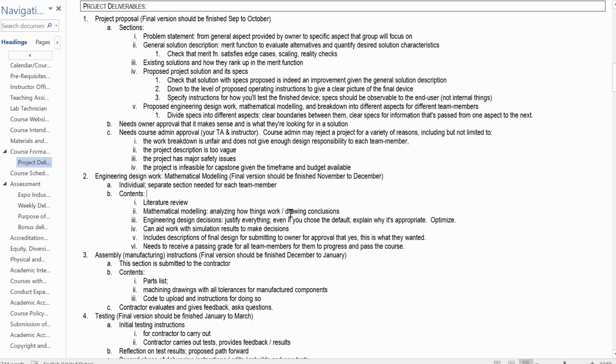So I realize that sometimes it's very difficult to model things. If you've already built the thing, it's hard to get help from this model. So definitely you're going to want to do this design work ahead of time. Imagine you didn't spec out the pump very well. You just kind of bought this pump. Fine. Okay. What could you do? You could calibrate it. Well, one way to calibrate it is with kind of an experiment to see how much water goes through for certain pump settings.